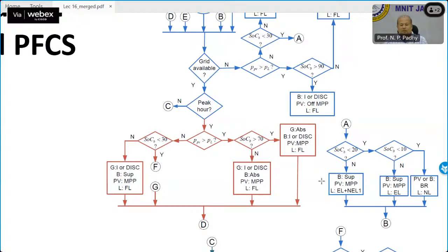Then I check the battery SOC, which is going to be 70%, meaning already fully charged or not. If the SOC is more than 70%, I'm going towards the right, a journey which is tougher and tougher. So the battery is already charged. The system is at peak, with excess PV energy available and the battery fully charged. Extra power from both sides. Let's see what we do. I think the grid will start absorbing. Am I right? This excess energy will go to the grid.